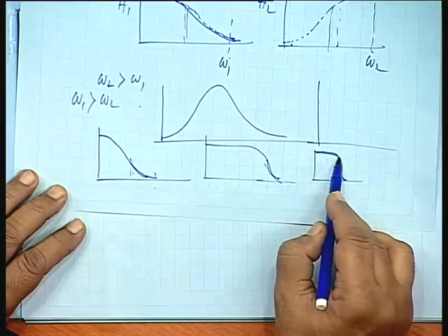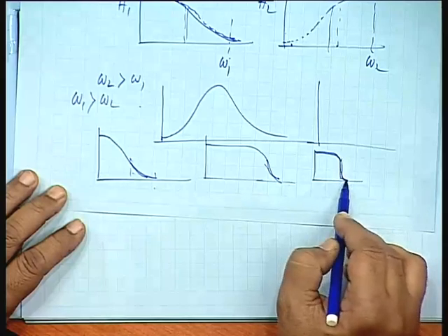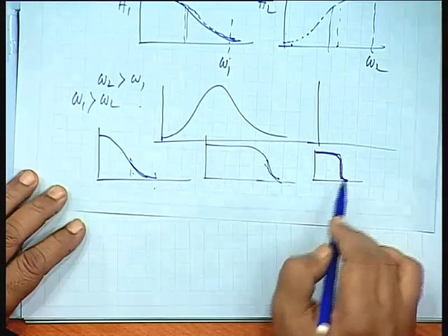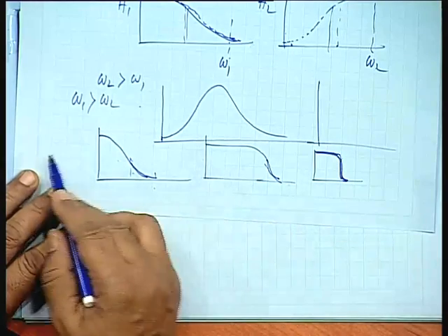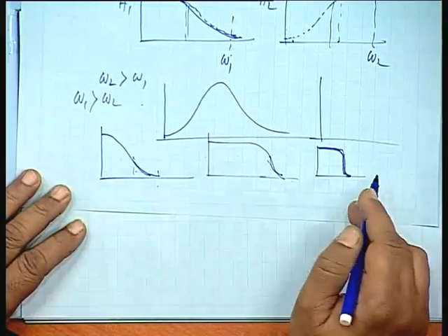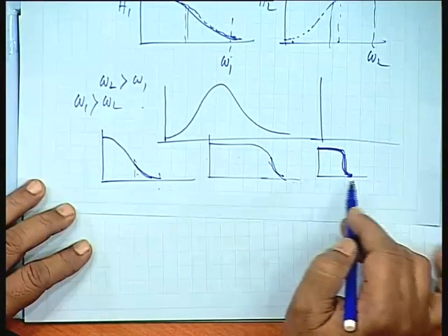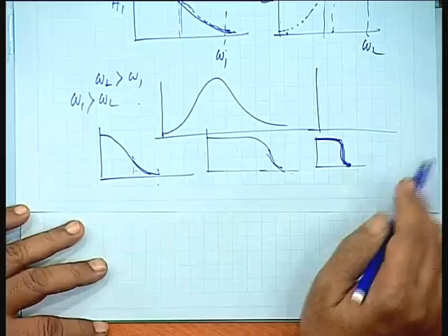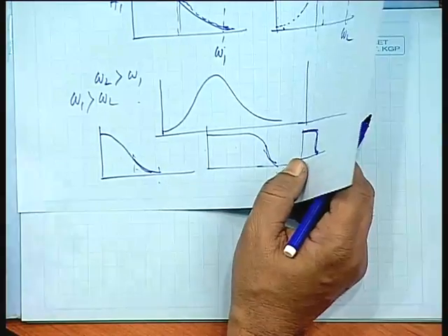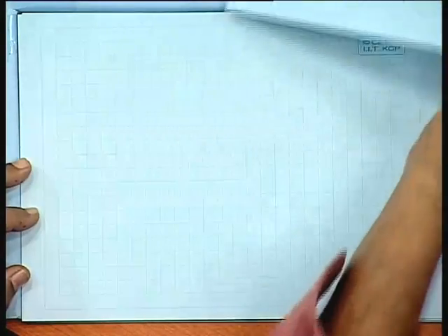So if you want to have a very sharp cutoff, alright, almost tending to an ideal one, then you can have 2 or 3 such low pass filters in cascade, alright. I can have the same filter function, square it, so H1 squared, H1 into H1 into H1, if I put the same H1, I will get the same filter function, but with much sharper fall, okay. So the roll off can be adjusted by having the filter order increased, okay.